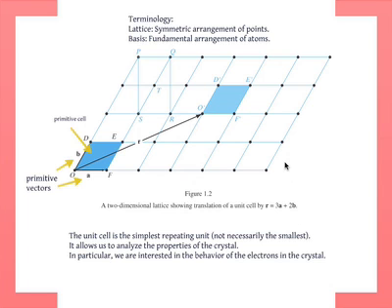Now, crystals are defined, of course, by the fact that the atoms are periodic. Okay? Now, in a periodic set of atoms, you can define certain basic terms to talk about crystals. And that's what we want to define first. The first thing is the unit cell. Because it's a periodic distribution of points, we know any periodic function can be defined by the portion of the function that's repeated, right? It's exactly the same way in geometry.